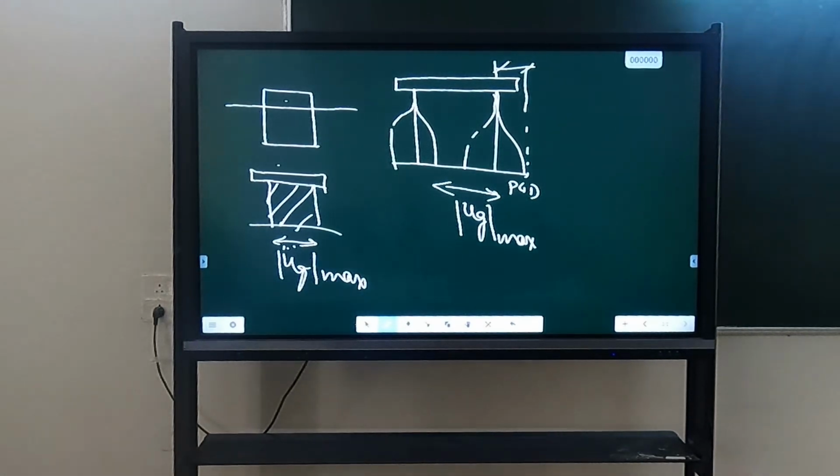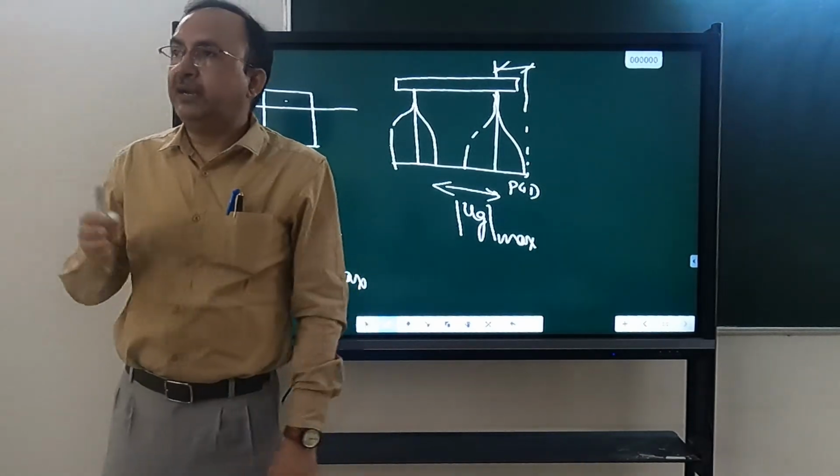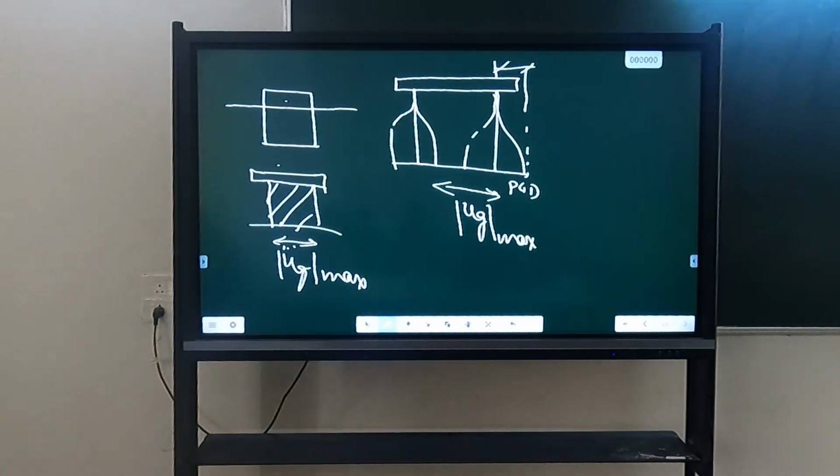The maximum change in the characteristics takes place at the interface from rock to soil, because there is the change in the properties, what we call impedance. So the impedance contrast is maximum. When the impedance contrast is large, that means the velocity in one medium and the velocity in the other medium are very different. Okay, then maximum reflection will happen. So this happens at every interface. It is not occurring at only one interface. On all interfaces, this happens.